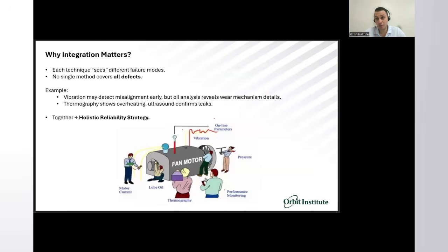Okay, so yeah, we all know why the integration between the techniques matters. It's important to understand machinery lubrication and oil analysis as well if you are a certified thermographer or certified vibration analyst, because integrating multiple condition monitoring techniques is essential, as it can see different aspects of equipment health. As you can see here, each and every one is seeing this fan motor from a different point of view.